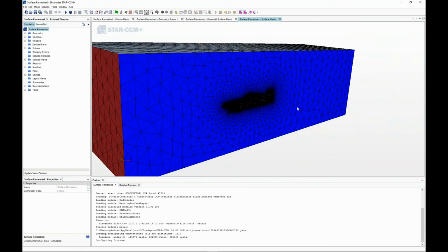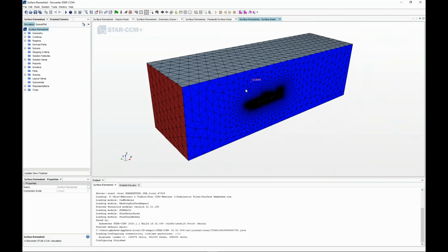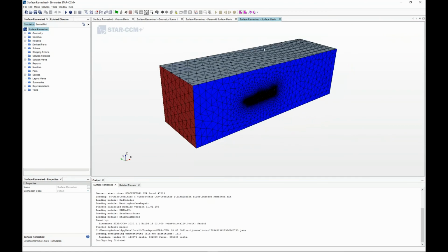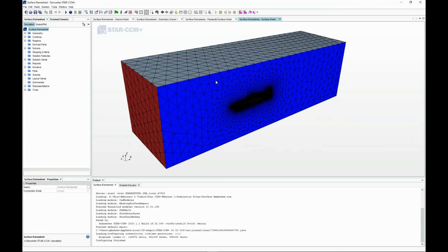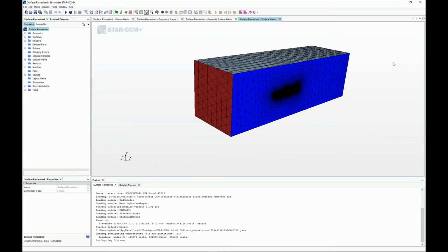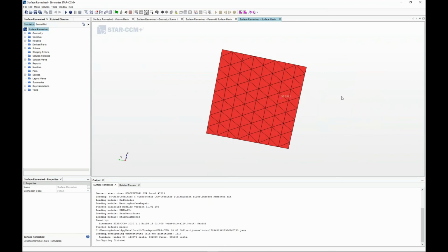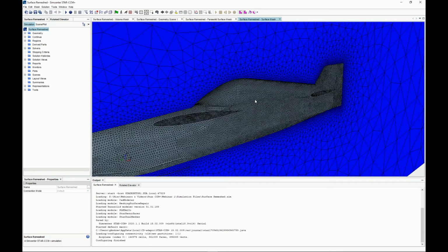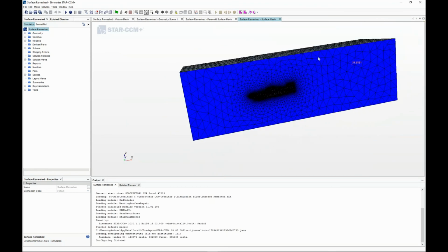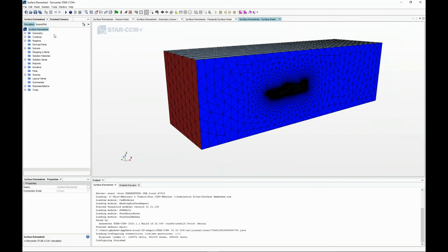All right, so this is more of a typical CFD simulation. You've got your domain, this big box, which basically represents a wind tunnel, or if it's large enough, just free field, a free field stream of fluid moving around this vehicle. I've actually got it modeled as a half model, so you can see this aircraft here. I've got a symmetry plane, and then an inlet and an outlet defined. And you can put this together in several different ways.